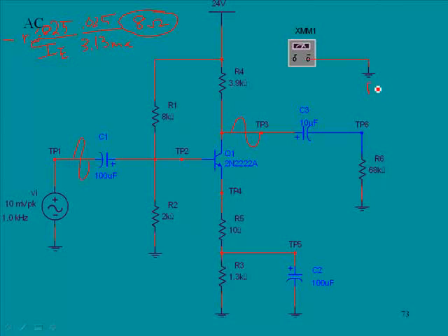So I'm going to put an RC over here. The lowercase rc is for AC resistance, and that will be 3.9K in parallel with the 68K. And that value is going to be 3.68K. And that will be our AC collector resistance.